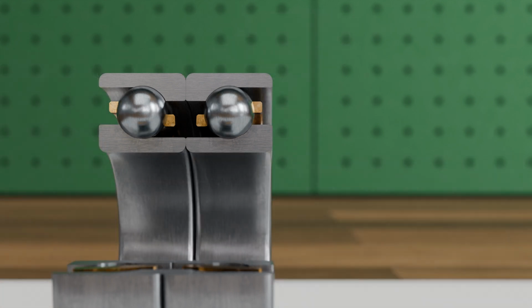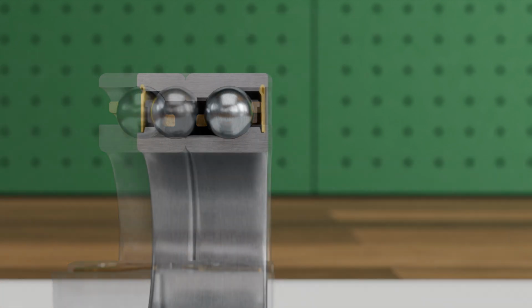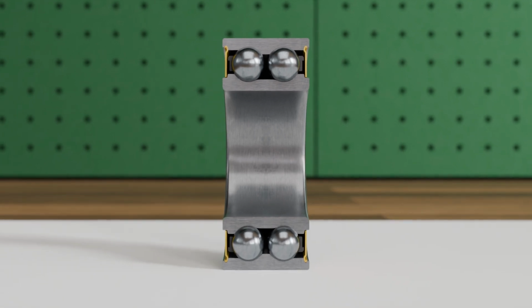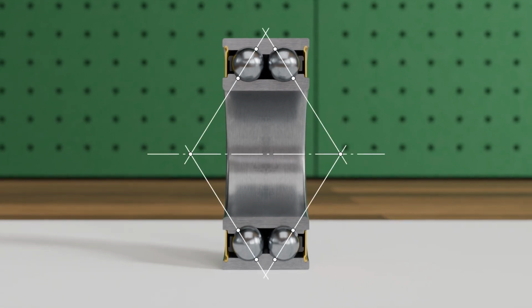Such an arrangement is also available as a pre-assembled bearing called a double-row angular contact ball bearing. The raceways are designed so that the pressure lines intersect outside the bearing, forming what is known as a back-to-back arrangement. In this arrangement, the intersection points of the pressure lines lie outside the bearing and form the load application points, allowing the support points to be virtually shifted outward.